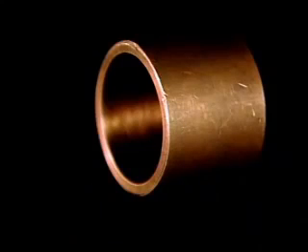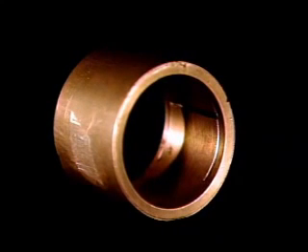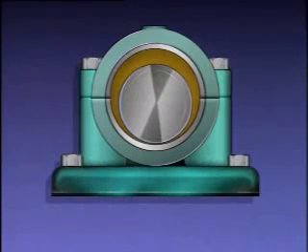Both the shaft and the bearing will last longer when friction, which causes wear, is kept to a minimum. This special type of sleeve bearing is a bushing. A bushing is a thin-walled bearing that can be removed in one piece. The grooves in this bushing collect oil and help keep the shaft lubricated. Now let's look at an illustration to see how lubricant reduces friction between the bearing and journal.